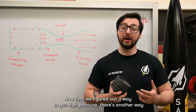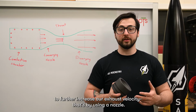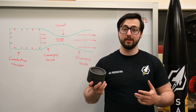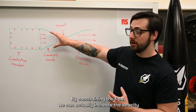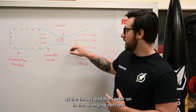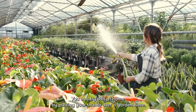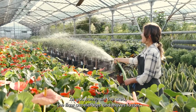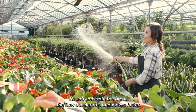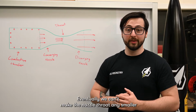Now that we figured out a way to get high pressure, there's another way to further increase our exhaust velocity, and that's by using a nozzle. By constraining the flow, we can actually increase the velocity at the throat and then later on in the diverging section. You can try this at home by putting your thumb over a garden hose. As you constrain the area, the flow accelerates and moves faster. Same principles apply to rocket nozzles to a point.